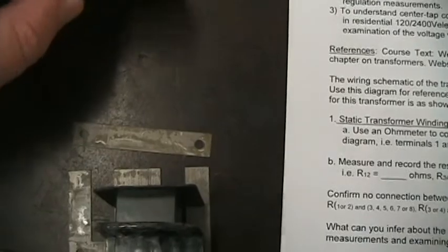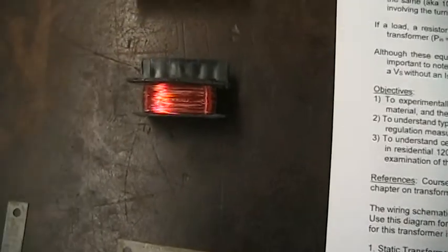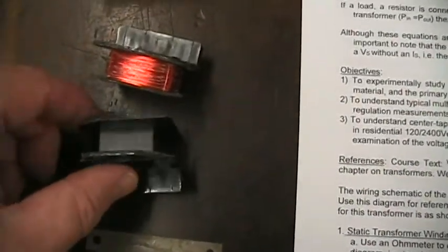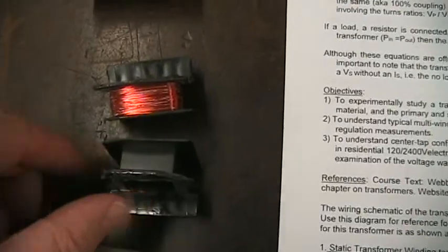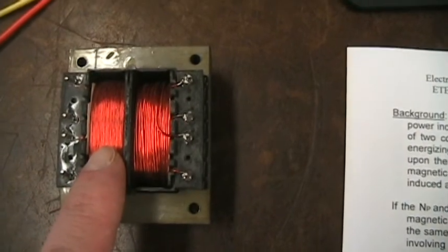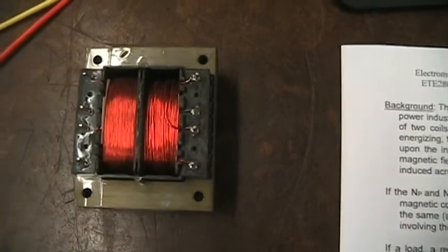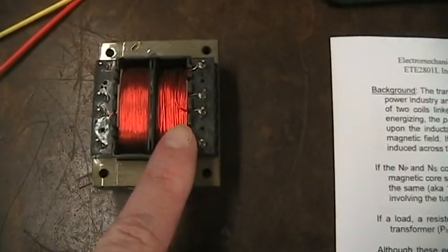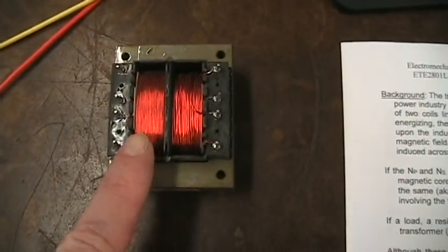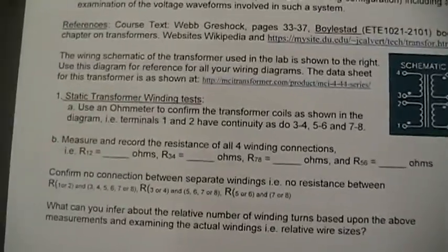Most of these manufacturers will wind the primaries as a common value because that voltage is usually known, and then the secondary winding is custom for the voltage that you want. So when we look on here, we see the primary, which is the finer winding, the higher voltage, and then the thicker wire is the output or the lower voltage. Lower voltage, higher current, higher voltage, lower current. More turns, less turns.